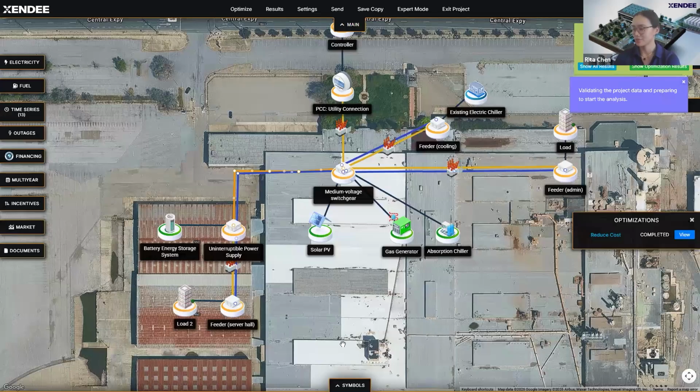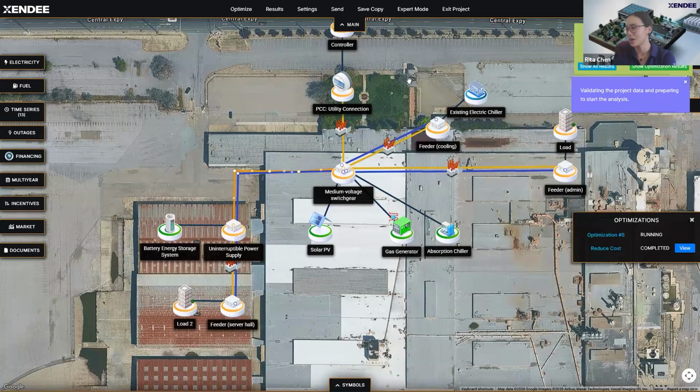Once you have that ready, you can go ahead and run an optimization. One thing to note with both multi-node modeling as well as when you enable power flow is that the optimization is going to take a little bit longer, especially the more complicated your model is, or the more DERs or constraints you have. It can take up to several minutes, whereas for single node models, which is what we did on Monday, most optimizations will finish within 20-30 seconds. So instead of waiting for the optimization to run, I'm actually going to...